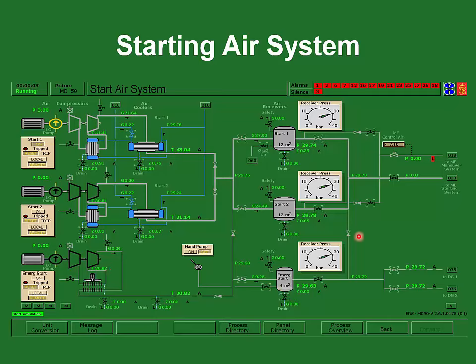These check valves, you've got 2 check valves on either side tying this into the main start air system. That green arrow is indicating direction of flow. So airflow from the main compressor can be used to fill this tank. But this tank can only go to the diesel generators. The green arrow is direction of flow. It cannot flow to the main start air system.